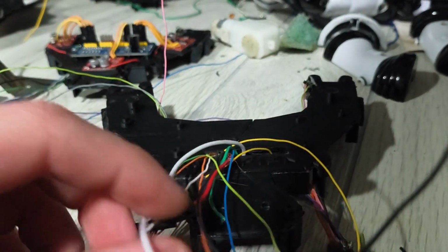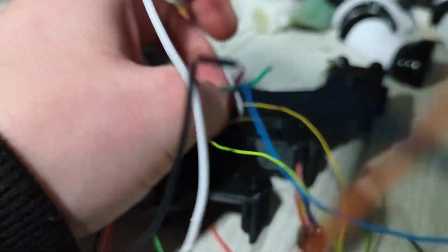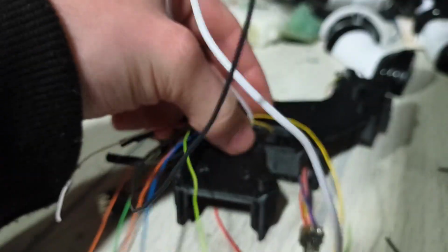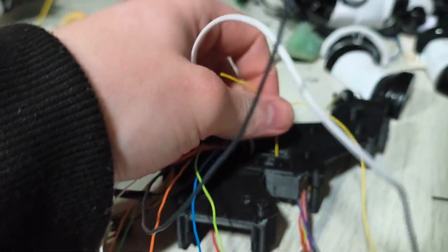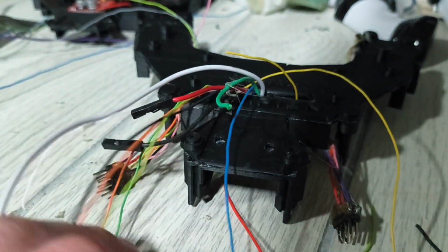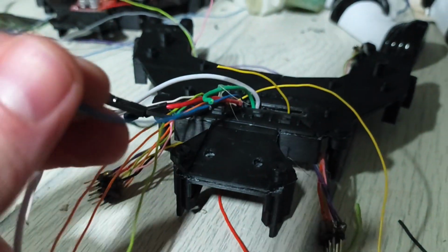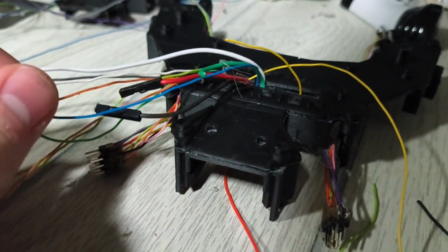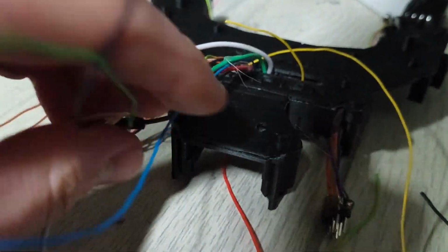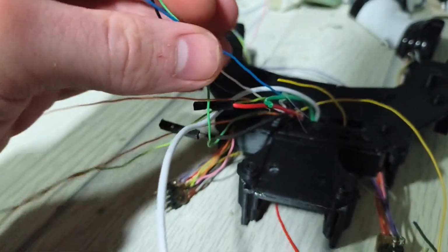Coming out of the rear of your robot, you need to have a voltage input that supplies power to the entire robot from the battery system and also reads that voltage. And then you need the PWMs that go to the single board computer. You need SDA, SCL, and all the I2C stuff. So here's that. We'll go ahead and grab SCL and then ground. And all of these will basically hook up to the I2C pins. So that's what those 4 wires do.